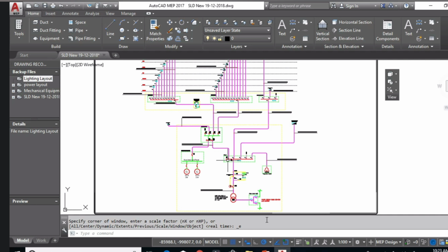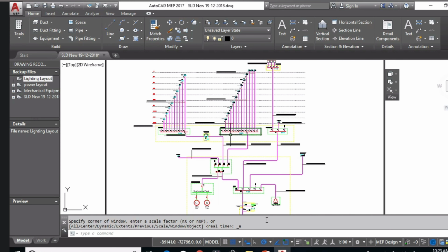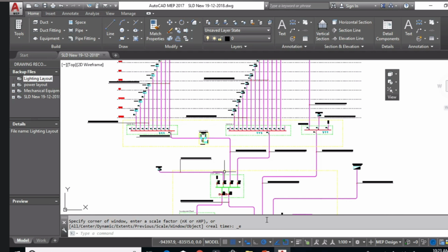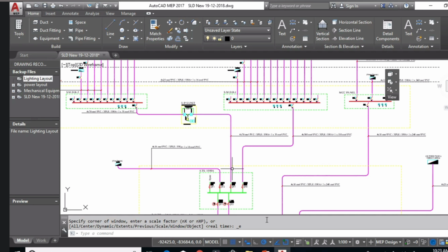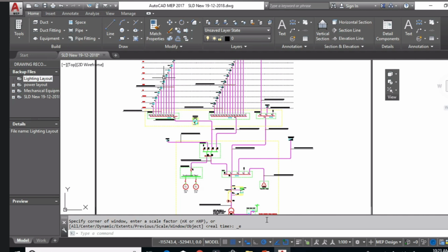And after that I also have an output going to the ATS system, and from the generator we also go to the ATS system, and after that I'm feeding two panels, one for the essential load, and here the another, as you see here, the output coming from the ATS directly to the UPS and to feed the other submain DBs or SMDB.